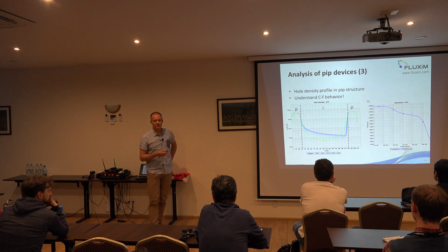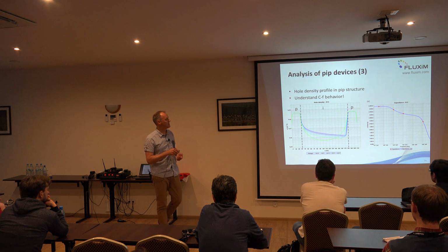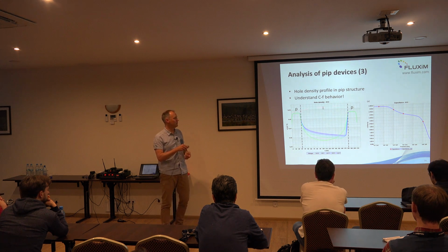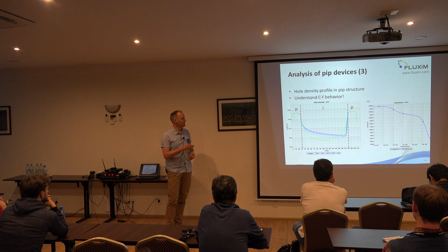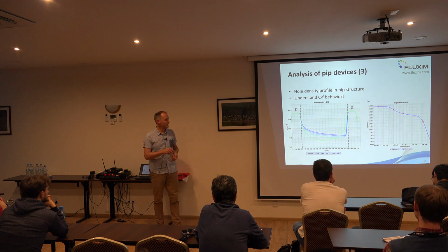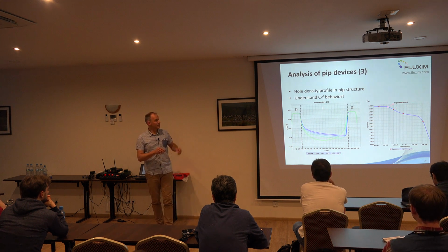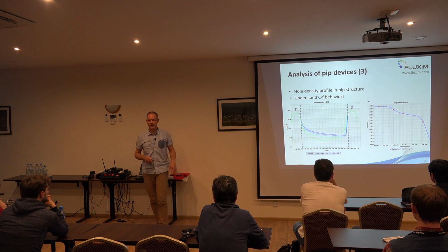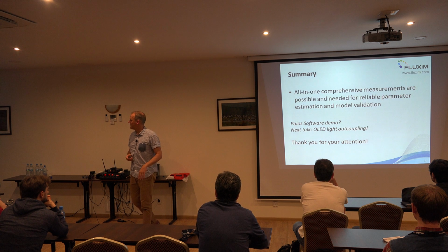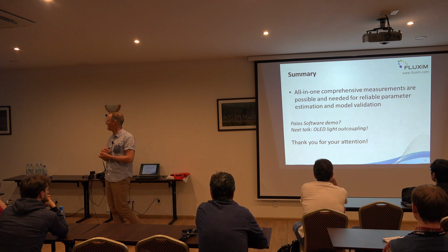And then you can also visualize the cross-section. How is the free carrier density of holes in the p-doped layers? How does it behave near the interface with the intrinsic layer, both at 0 voltage in green and at high voltage in blue? And we can also take profiles at different frequency to understand why we have an increase of capacitance. Okay, that was the last case study.